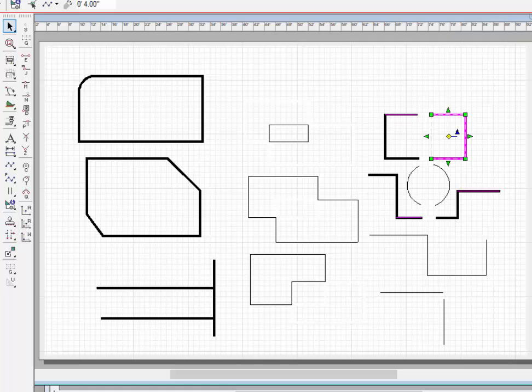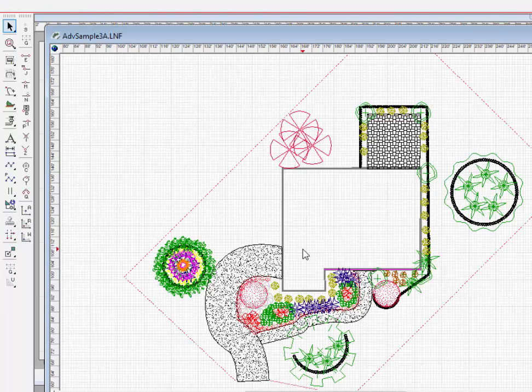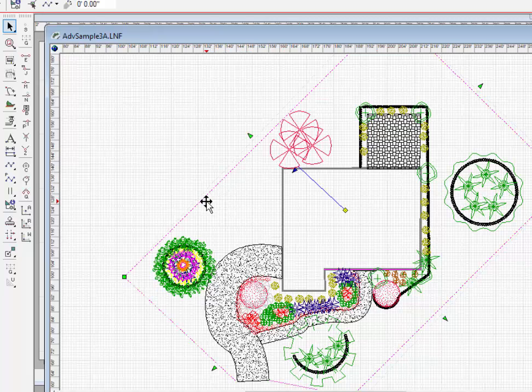Let's go ahead and show you an example of what we can do with the Trim Channel tool. Okay, so I have a drawing here and I want to only do the front yard. I really don't need anything from the backyard here. Now if I go in and I select the property line or the foundation wall and delete them, it's going to delete portions of the wall or the property line that I want to keep. So I need to basically crop or trim portions of this.